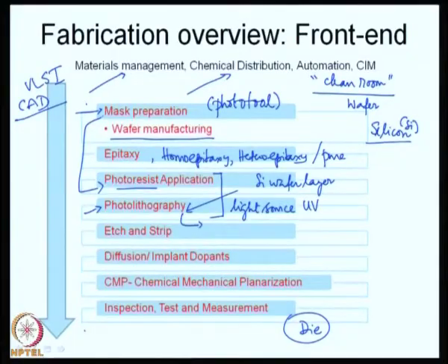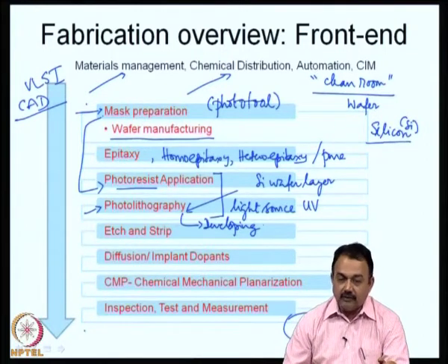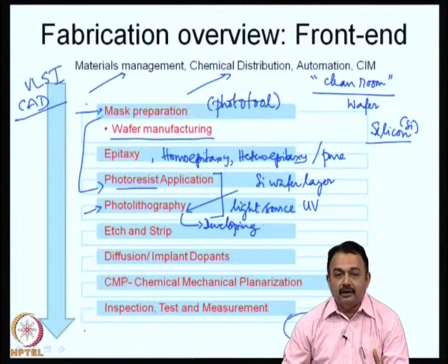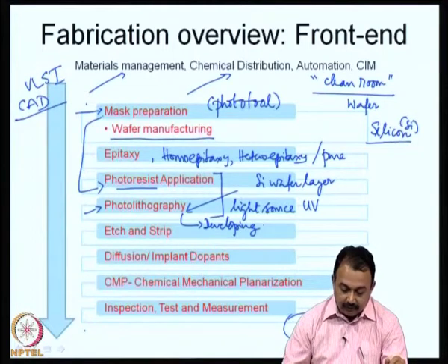Therefore, those areas which are exposed to UV light will get physically changed, and therefore, they are also going to react with certain chemicals during the process of developing. So, the next step, photolithography also includes a step called developing, which will now define the image that you want to generate. Okay. So, this is a very important step. Defining your image on the substrate using photolithography will be a very important step in the transfer of the image, and therefore, the yield rates are very critical at this point.